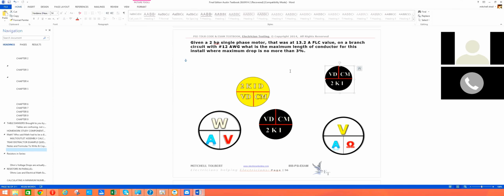So I see 430.248, full load currents in amperes, single phase. And that's a good table. And then 430.250, full load current, three-phase alternating current, on page 351. Yeah, those are the two tables. The one that's on page 350, that's 249. You can X out 430.249.